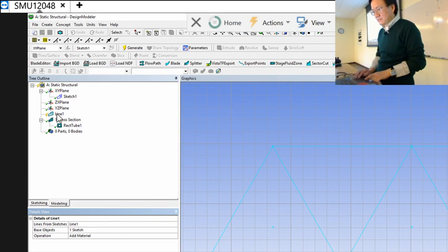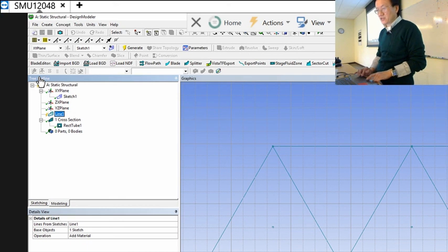So once you've done that, you see you need to update line 1, that you use to create your structure, your body. So right mouse click, you will see generate. Now you generate truss structure base model, base body.